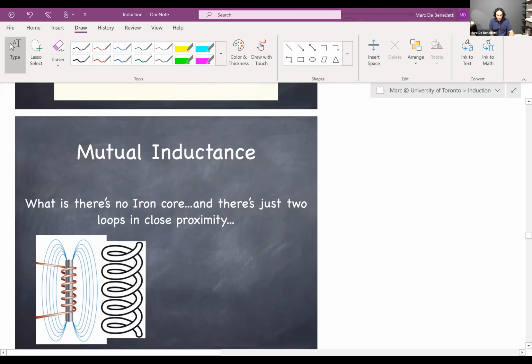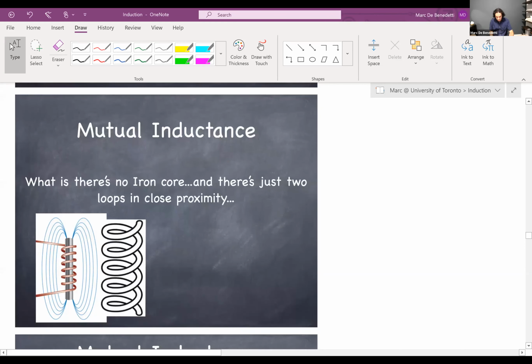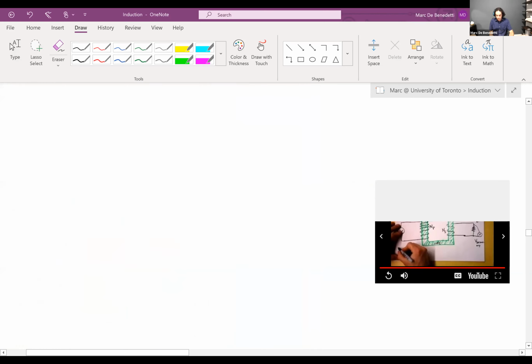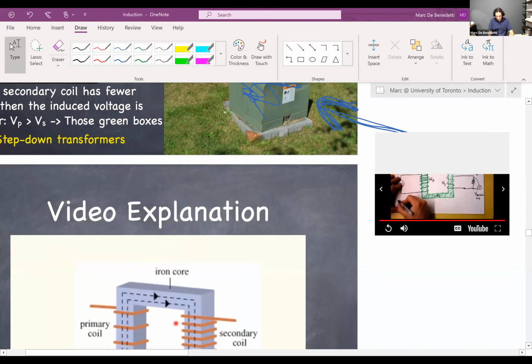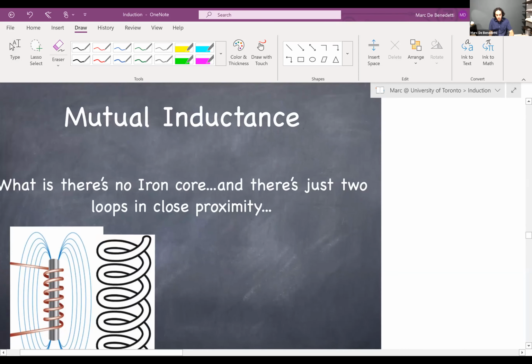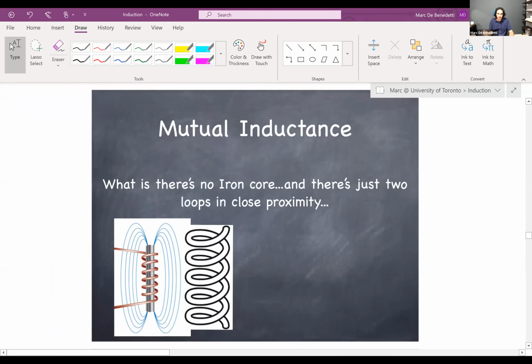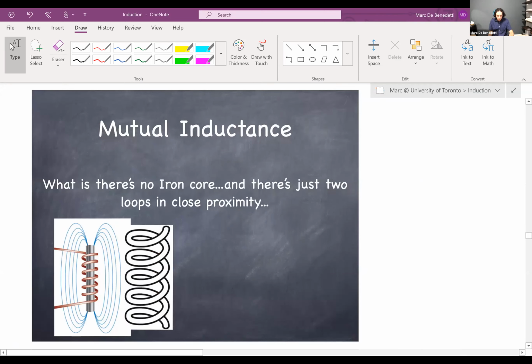So this brings us to the last sort of subchapter in transformers, we're talking about mutual, oh, what's going on? Okay, we're talking about mutual inductance and self-inductance. That's kind of like the last little chapter. So mutual inductance is a way in which we can just quantify the phenomenon we just talked about. Okay, in a properly designed transformer, we know that that flux transmission is perfect, right? The flux felt by the primary coil is exactly the same as the flux felt by the secondary coil.